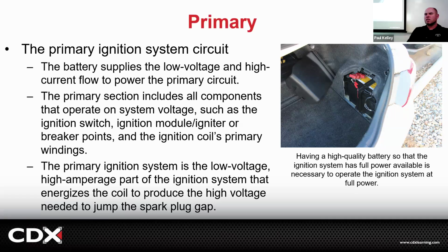And then the other thing was, it's in the wintertime and I wear a heated jacket. You can call me soft if you want, but that heated jacket pulls a lot of battery voltage. So when it stumbled, I was thinking about all these things, and I've had the alternator type of part fail before. And I was like, you know what? I wonder if I'm not charging. So I disconnected my heated jacket, boom, and I punched it again, and it had quite a bit more power.